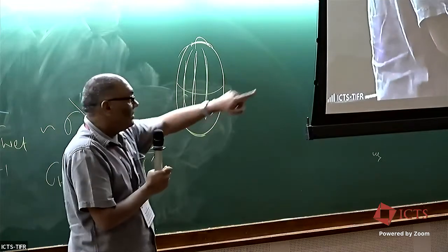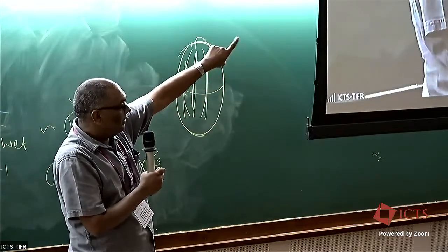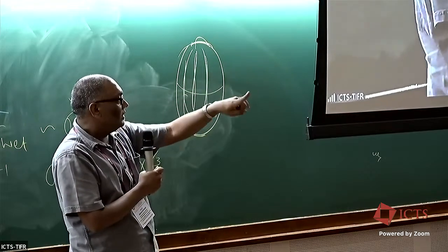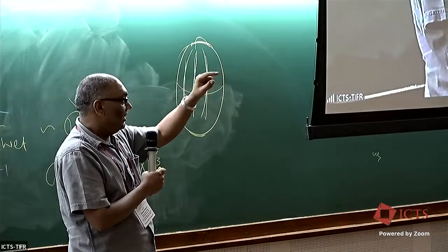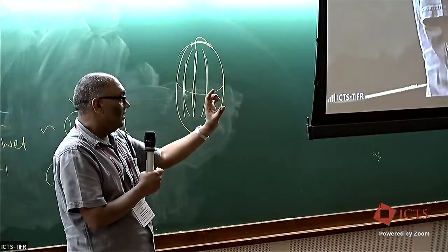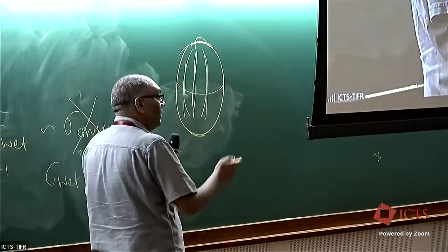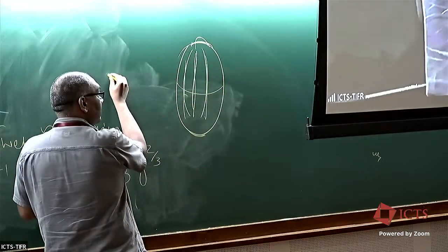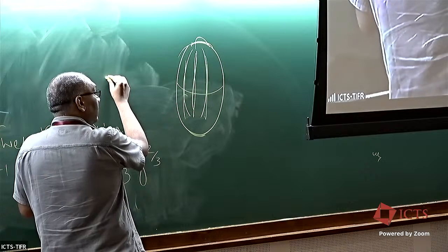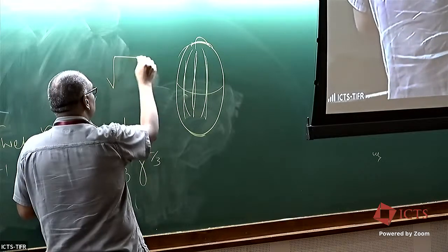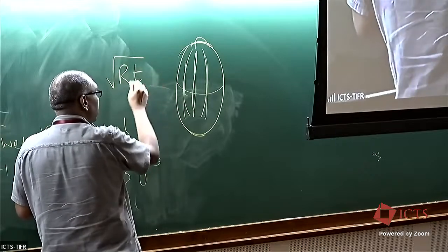So something along the same lines was happening for the sheet that was wrinkling, but there are fluctuations that amplify in the end to give you the triangular, three-point shape. The point where I got stuck was, is it due to the length scale that emerges due to the competition between bending and stretching, which is the square root of radius times the thickness?